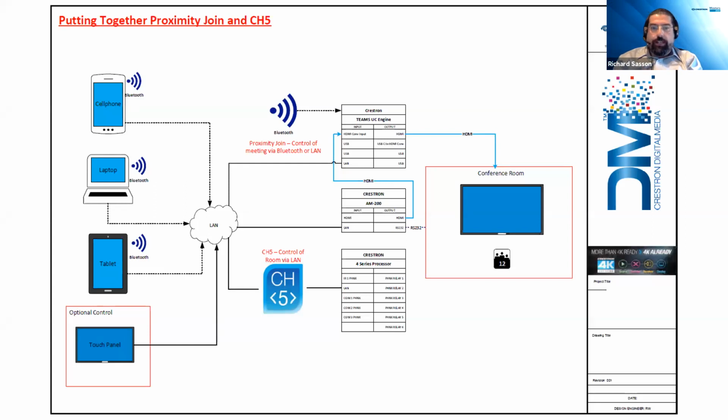I see a lot of questions, people asking, Sean, why do we show 232 to control display devices? And why didn't we just do CEC control? It's an option. It really is. It's kind of shown as a dotted line as an option, folks. I know you're asking that. I got that like 5 or 6 times, but it is an optional way to control. It's not that there are two 232 lines going to the same TV. It is separate lines going to it. But again, it's an option that you have.